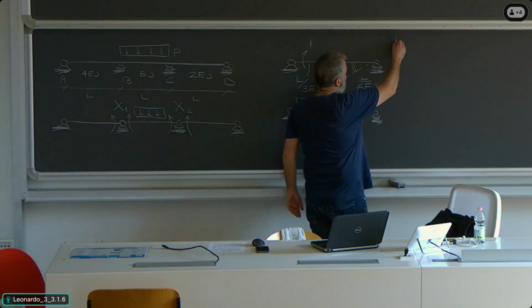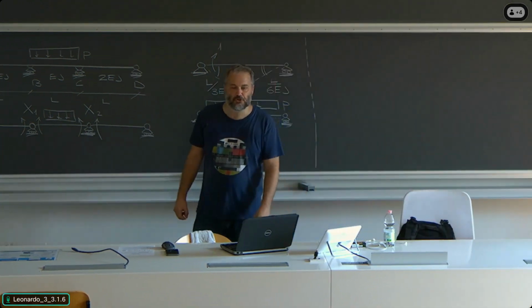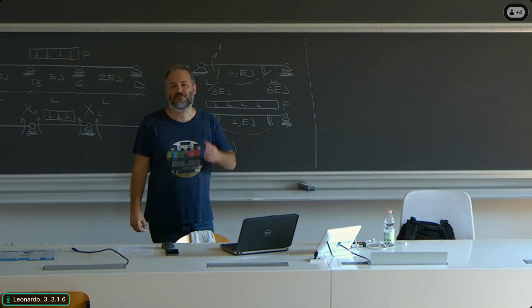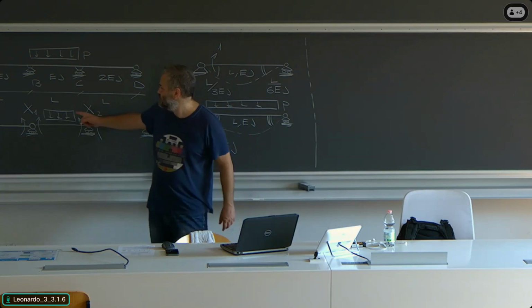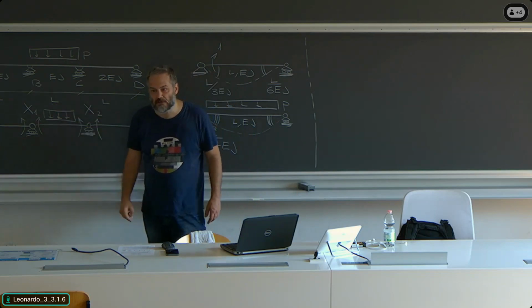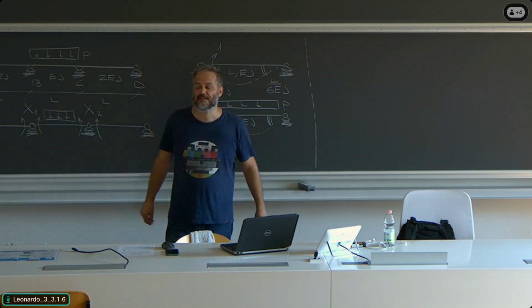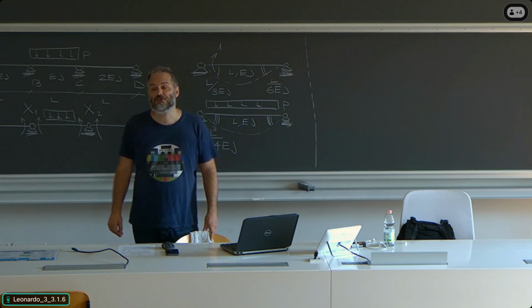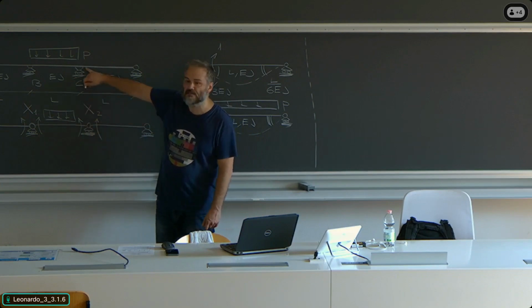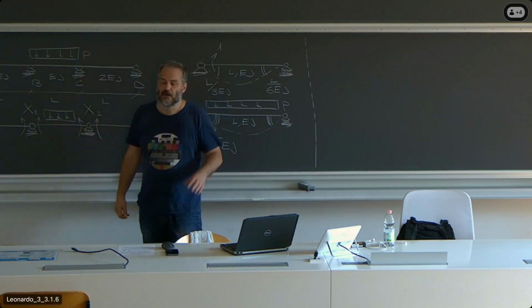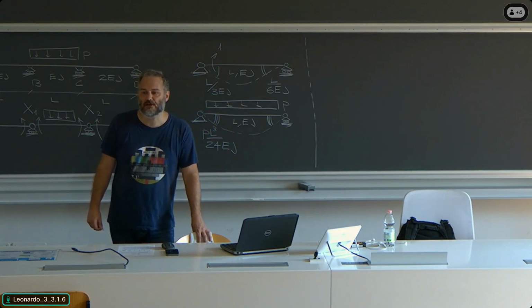Now, how does the solution go? We use an approach which is based on considering the different loads acting on the structure, and by loads I mean the two unknowns and the distributed load, one at a time. Then we superimpose the effects and we write compatibility equations to reinstate the continuity which we lost by moving from this structure to this one. I will try to point out what it means that we have to reinstate the compatibility.